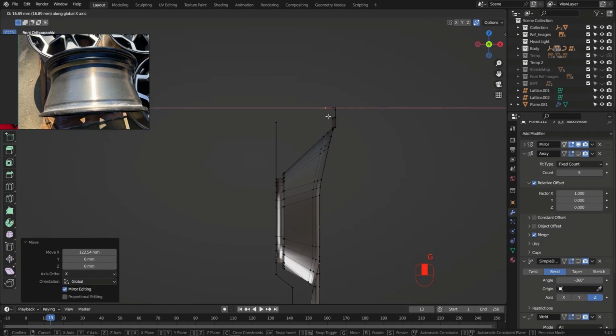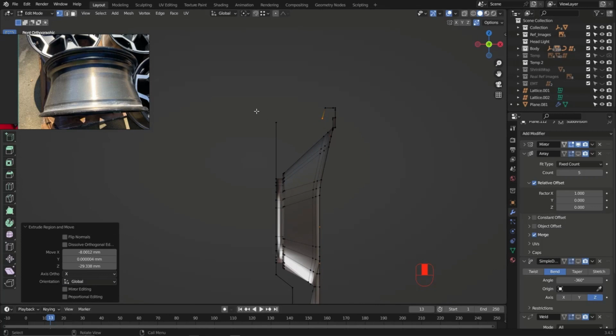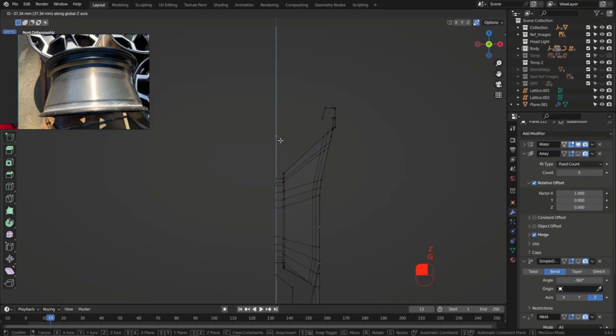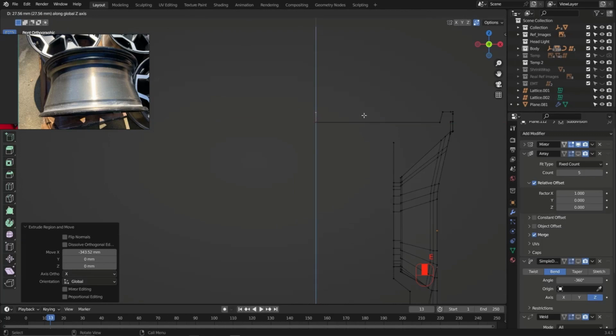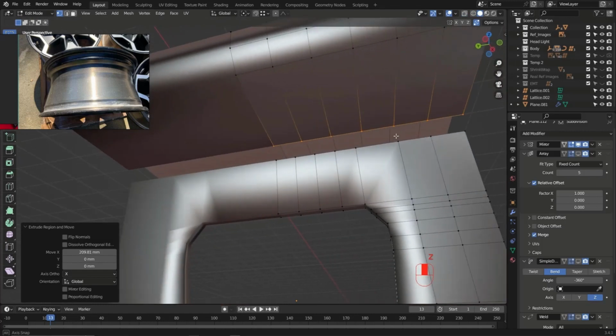All I'm going to do is extrude this like that. In the wireframe mode, maybe I should take these down just a little bit and focus on this area and extrude this to this direction, I guess. And then extrude this up, hold Control and snap it like that, and let's move this a little bit like this. Hit E to extrude this again. And then another E to extrude this like that. And extrude this again like this. And now maybe we should merge those together.